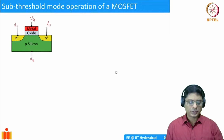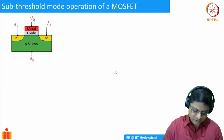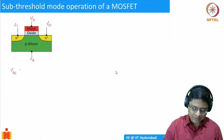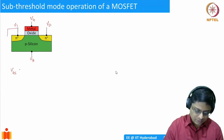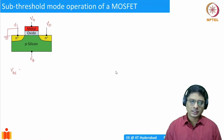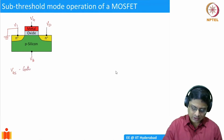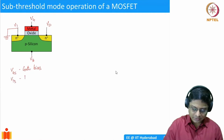Typically, what we do is we take the source as a reference. So what we will refer to is VGS. This is typically what we will use. So what we end up doing is we ground, let's say, the source here. In the case of an NMOS device, we ground the source, and then we talk of the gate voltage relative to the source voltage. So this I'll call the gate bias, and then VDS is basically the drain bias,